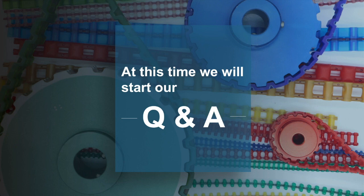Another way that the sprocket material matters is in the environmental compatibility of the system, both for temperature and corrosion resistance. One thing you want to make sure is that the sprocket has adequate corrosion resistance, so that through the life of the system, it doesn't generate corrosion products on the sprocket teeth that could be abrasive to the belt and actually cause the belt to wear out sooner than the expected life of the system.